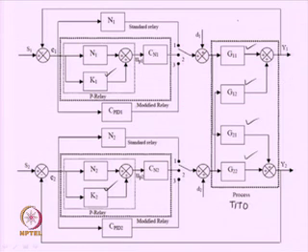parameters set the PID parameters, and then connect the switches to number 3 and run the system, your TITO system. Then your TITO system will have a decentralized control system having suitable controllers in the loop.